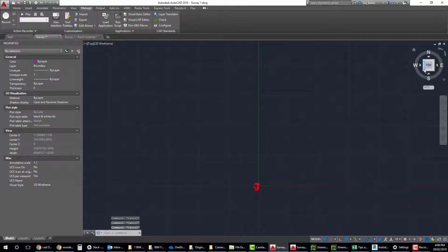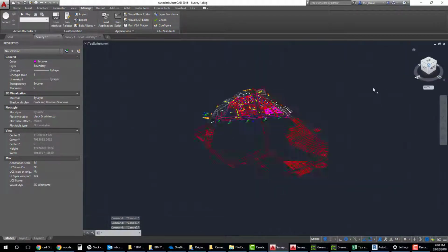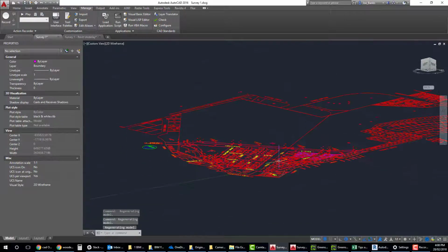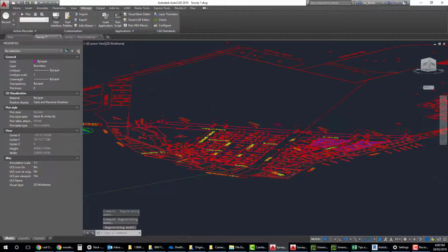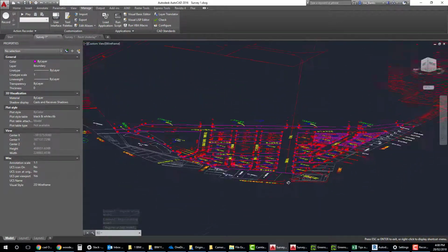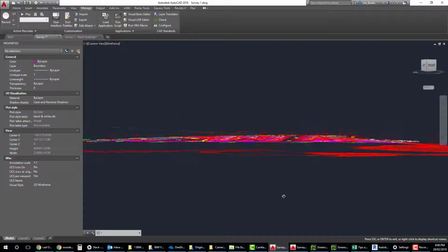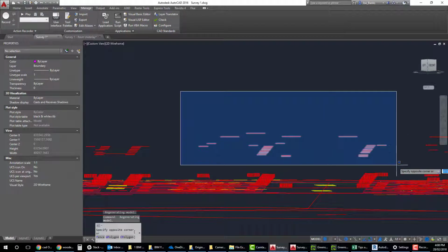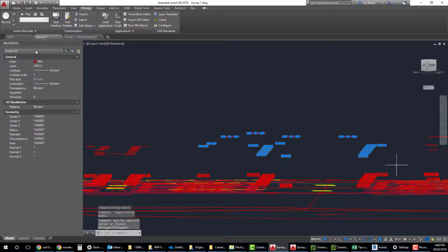The other thing I always like to do is to have a look at this from the Z direction. So you need to make sure that everything is at the right heights. If you've got contours, etc., that they're actually showing up at the correct levels. You can see here we've got a lot of geometry that's just oddly at a different height. You can flatten these objects out. Some quick ways to do it is by picking something like circles.